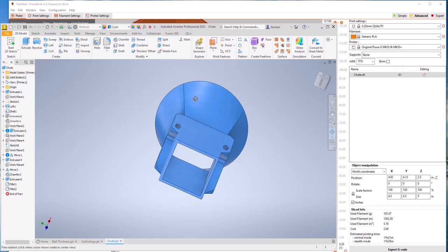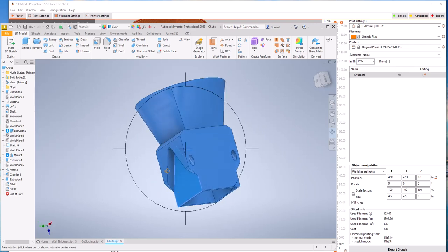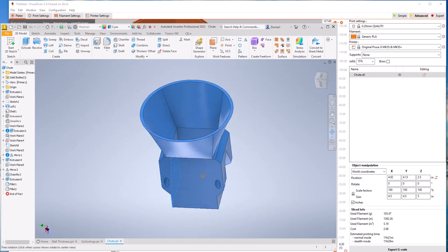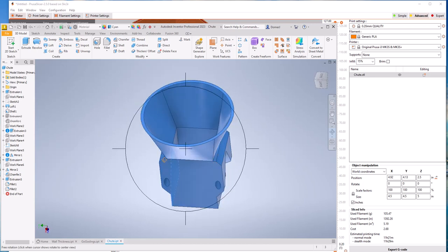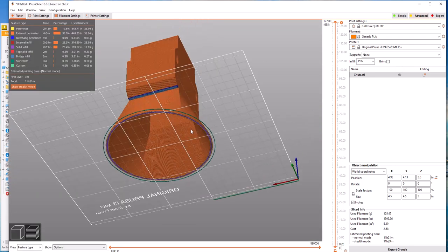I would say that is not the correct orientation. The way it's designed to have all these draft angles and such, it should be printed from the other direction. And there's technically this flat right there, which is maybe a design flaw, one could argue, but that flat is not going to print well upside down. So that flat, as you can see, is going to have an issue unless we turn supports on.